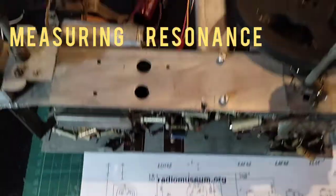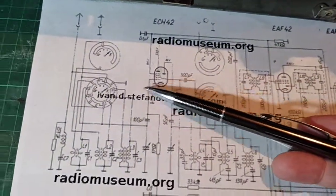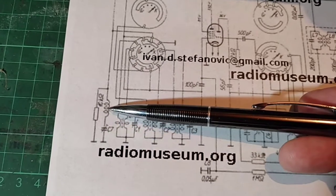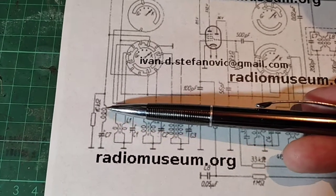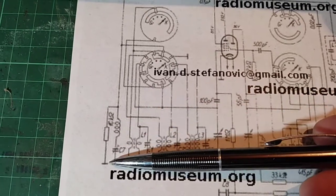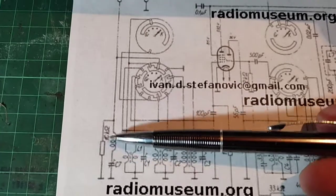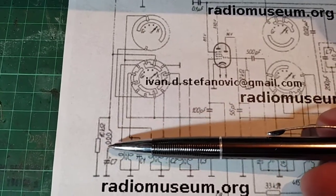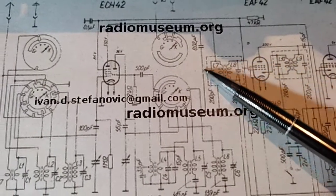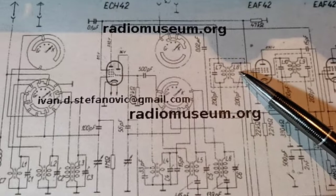So I have this tube radio, Tesla 55C, and I have pulled out this coil and capacitor because the coil was broken at one place. I've repaired that, and now I need to determine at what frequency this coil and capacitor resonate, because they should be tuned to the intermediate frequency. That is the frequency that is going to be amplified in this part over here.